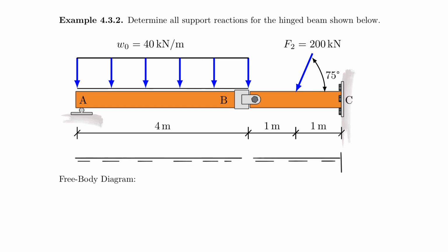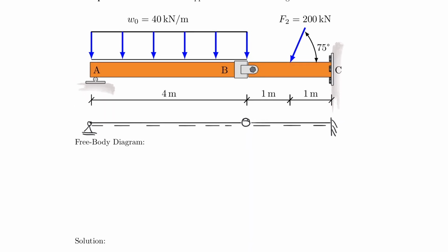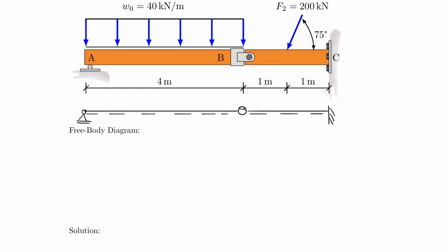So first on the right side, I have a cantilever support or a fixed support, and then I have a hinge here, that is my circle, and then last but not least, I have a roller here on the left side. And this is clearly not a free body diagram, because a free body diagram has forces in it and not symbols. So I'm going to copy this now into my free body diagram, which of course still has the dashed line because it is a rigid body.